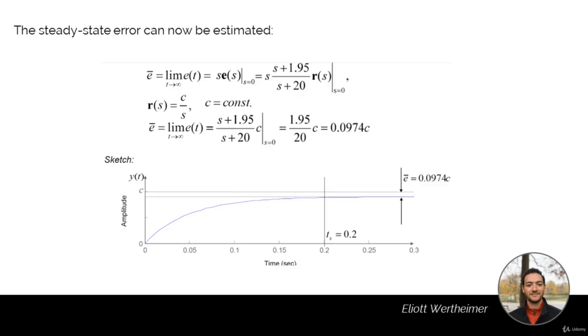And this is a consequence of proportional control. It is very, very hard to get a perfectly zero steady state error, simply because proportional control doesn't actually look back on your error. It doesn't know your long-term error. It reacts to an error that is happening right now.